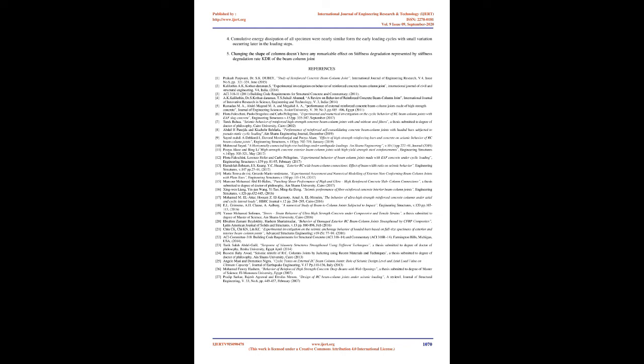Strength decay. As noticed from the load displacement hysteresis loops, the peak strength increased as the applied displacement increased until ultimate capacity level was achieved. Reinforced concrete beam column joints exhibit progressive loss of strength under cycles of inelastic deformations. Beyond this level a decay in the loop peak strength was observed. The degree of strength decay depends on many parameters including the dominant response mode, confinement, and strength of concrete, history of cyclic load and level of axial load.